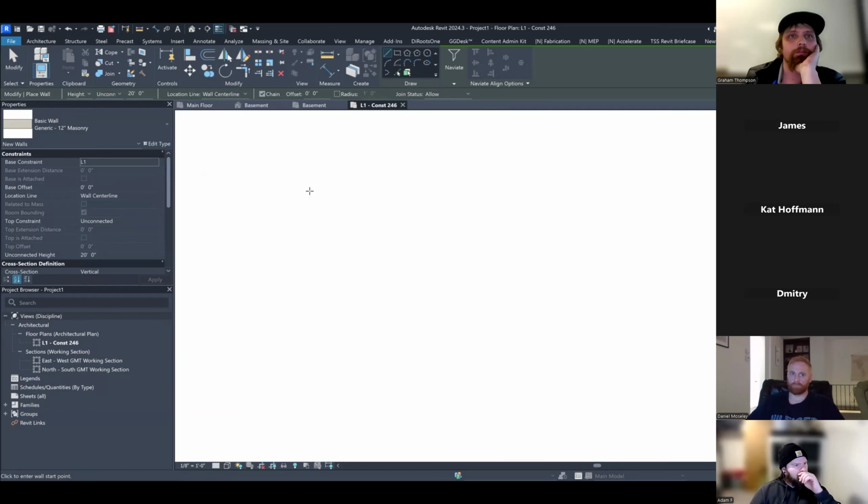So we're going to start here, and I'm going to draw this whole thing, and I want you to realize what I am doing as far as clicking. I'm going to click twice in this entire command. I'm going to draw all these walls with 2 clicks: 1 click to start my walls, 1 click to end my walls. Everything else that I'm doing is direction and distance. So what that means is I'm going to give it a direction.